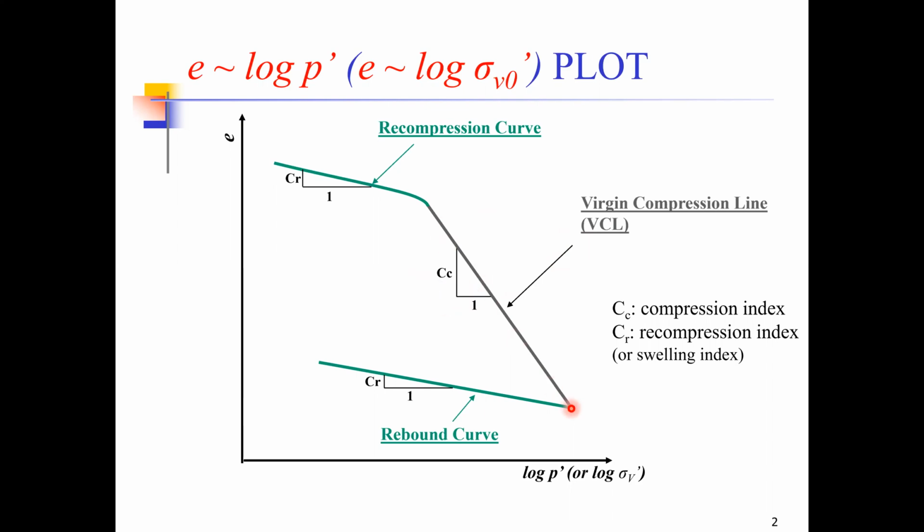However, after applying this load, if we unload the soil sample, we see the swelling of the soil sample upon unloading. So you see, when I'm unloading the sample which was initially being compressed because of the application of this load, the same soil will try to expand. The expansion of the soil sample is not the same. It is not equal to the compression.